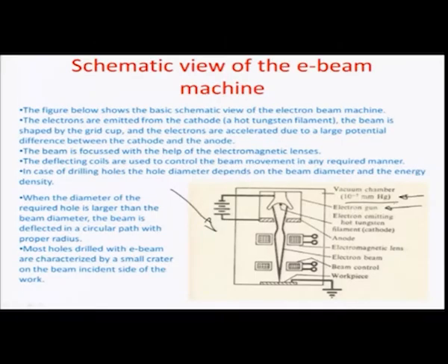There is an electron gun which operates on the principle of thermionization, meaning thereby that this gun is heated. On its surface there is a filament, and this is also the cathode, which is electron rich. You can see the way this power supply is positioned, making this the negative electrode, and so there are huge amounts of electrons existing in this particular region of the electrode. There is a hot tungsten filament which heats this cathode so that it starts thermionizing the material, and electrons come off by virtue of thermionic emission from the surface.